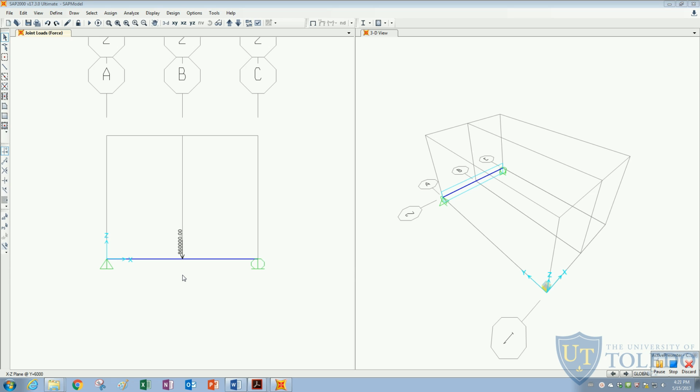Since we only have one force in our problem, they shouldn't yield different results in terms of capacity of this beam. One advantage of the displacement-based analysis is that because we are applying displacement and calculating the force that displacement causes on the beam, once the beam fails, we can still capture the post-failure behavior of the element.